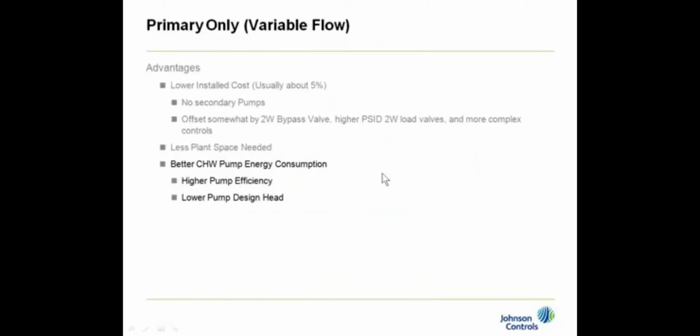There's also the issue with the pump efficiency that the primary pumps being at lower heads of, in this case, 50 feet, is going to have 1,200 RPM motors, and it's going to be lower down in the pump curves. And generally speaking, you're going to see a lower efficiency on those pumps. In this case, let's just assume that we'd be in the 70s. Let's pick 74%. But when you add the 74 against 50 foot head versus the 100 feet at 80% for the secondaries, then you have an overall efficiency improvement by going to variable primary flow on the pumping system.